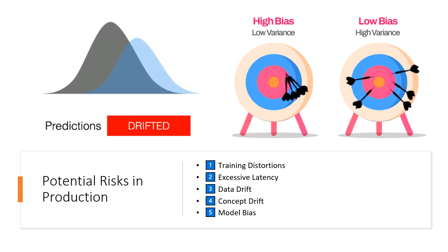Data drift. Changes in materials, lighting conditions, or reflections can alter image characteristics in unexpected ways. For example, a new type of paint or a specific surface curvature may reflect light differently, causing saturation effects that confuse the model. This may require camera adjustments, improved filtering, or repositioning of light sources.